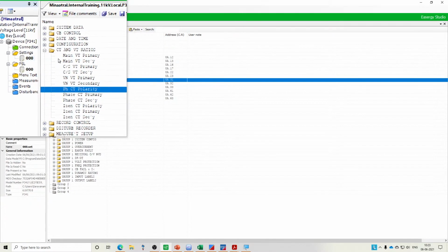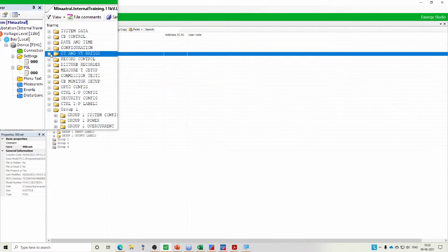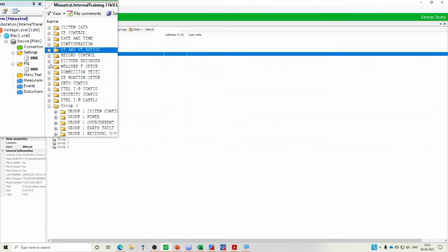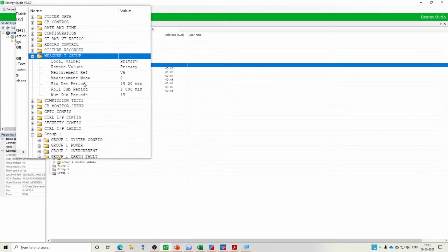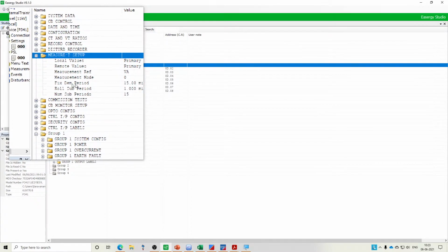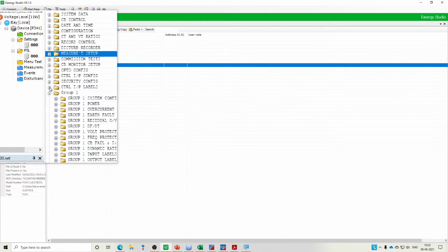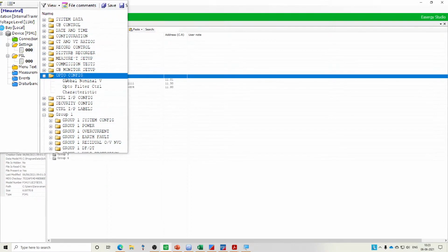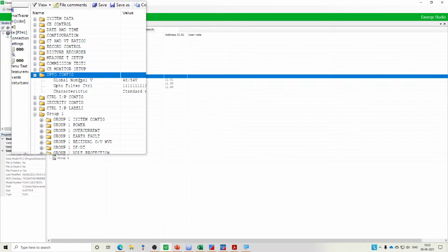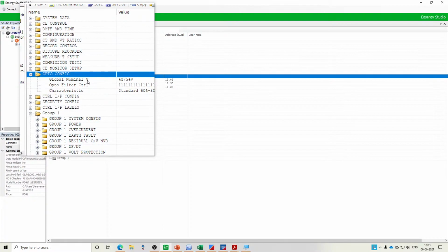Once you have set all this, what you have essentially done is configured your analog inputs. There is a lot more to this. You can set up your measurement, that is how you want to display it and what the measurement reference is. The next one we will go to is your binary inputs. Here you'll be setting the nominal voltage for your inputs, as we all know, DC voltage, which is how inputs usually function.